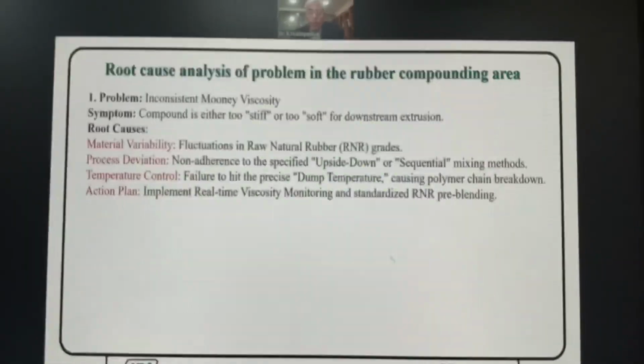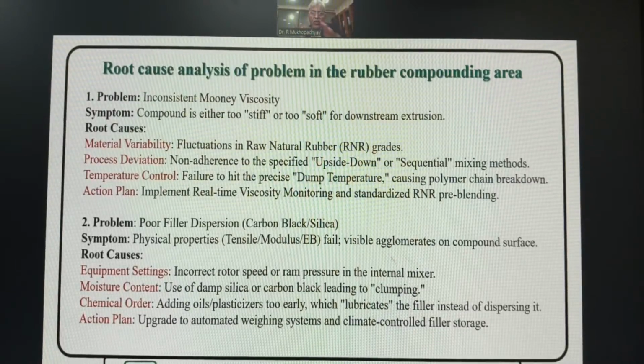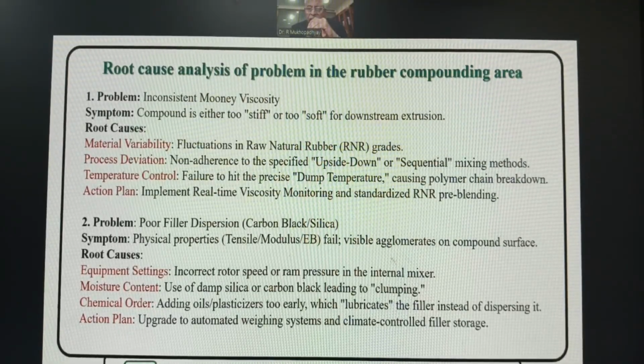Then the root cause. Suppose you get inconsistent viscosity, what do you look for? The compound is either stiff or soft. Then the material reliability. Second is the process deviation. Third is the temperature control. Then real-time viscosity monitoring and standards.